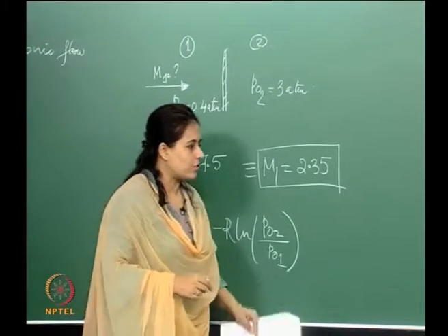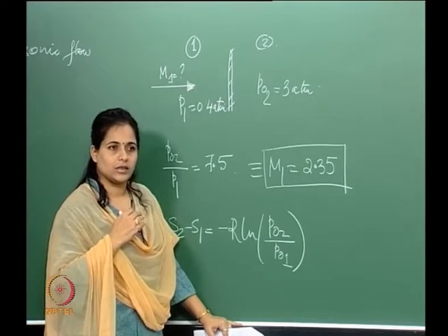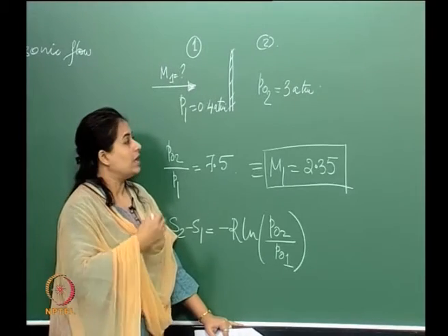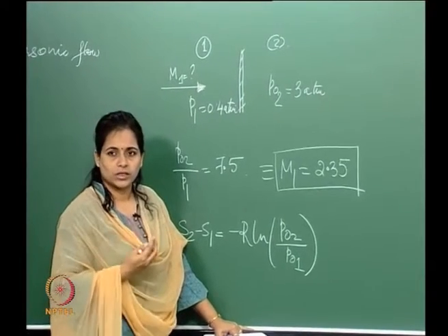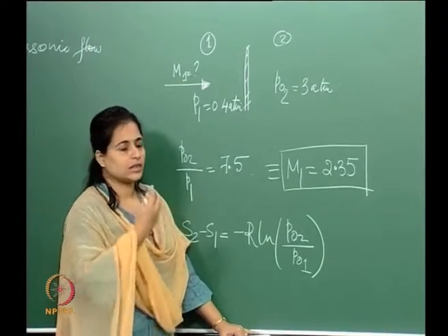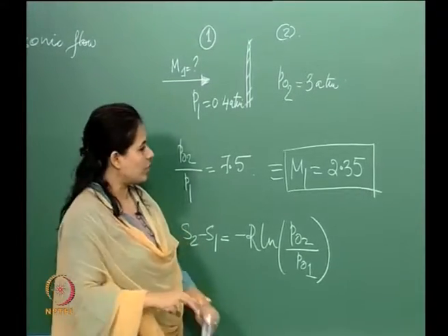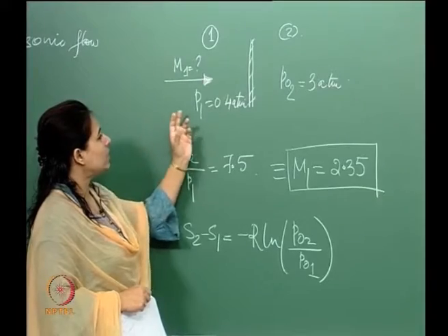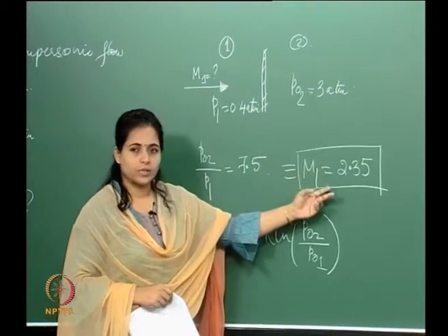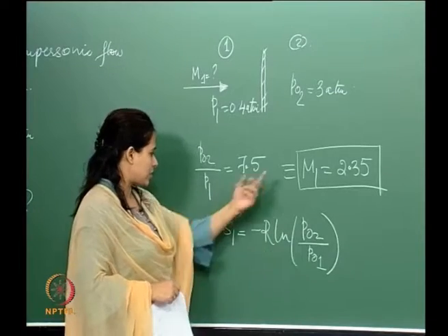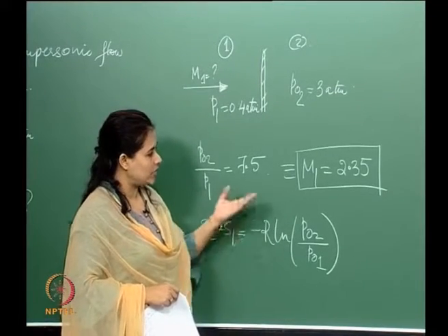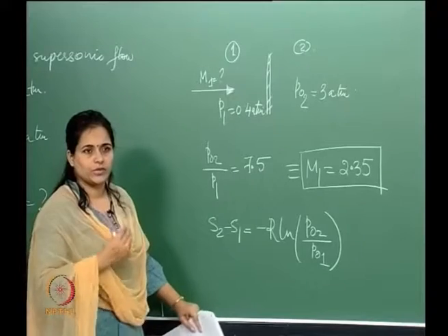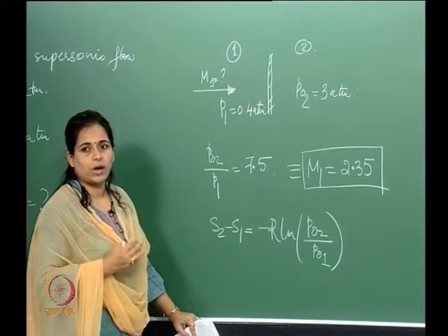Now what we have done so far is we've connected the temperature changes, pressure changes, density changes, etc., as well as the total pressures, temperatures, densities, etc., across a shock wave in terms of the incoming Mach number. So we got these ratios, we calculated the corresponding Mach number, and we therefore got the corresponding entropy change. We did exactly that just now. So everything that we've done is in terms of the incoming velocity, the Mach number, etc.